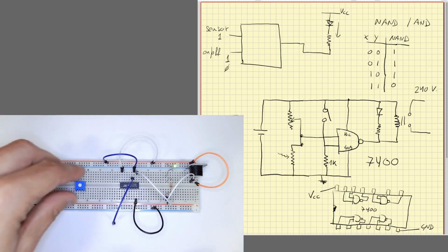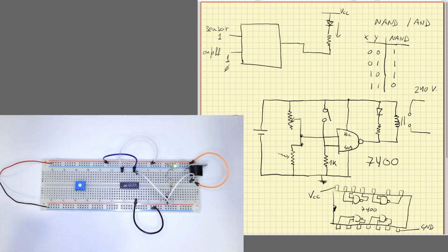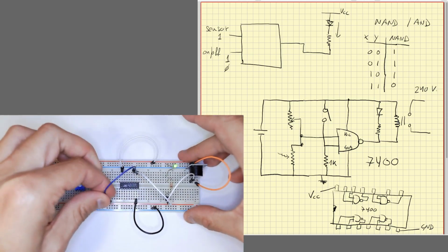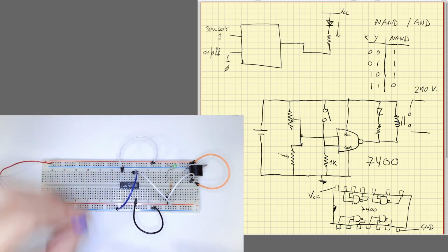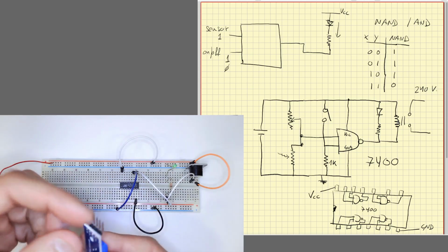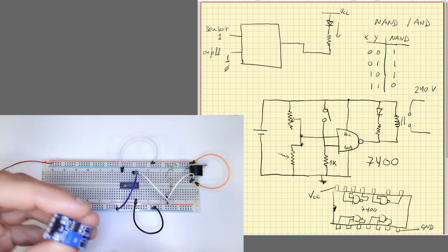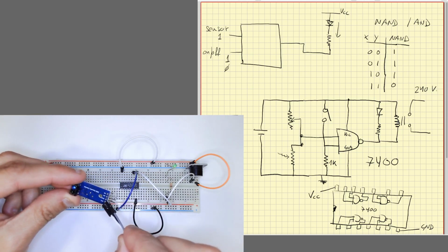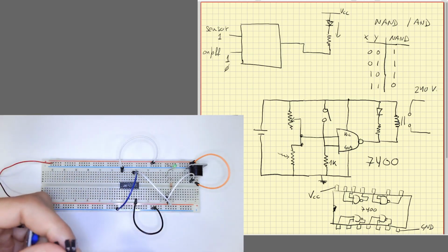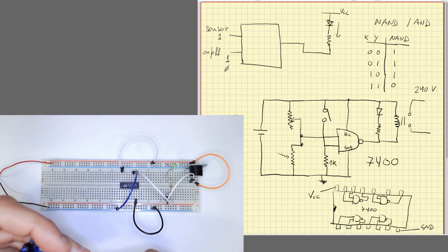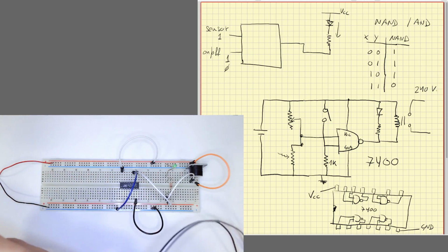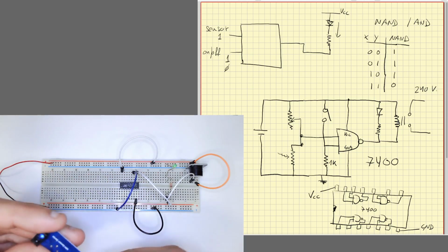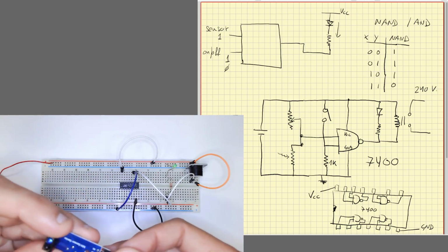We'll remove all this. We will switch our system off. And these sensors already have the terminal. We have to give energy to the sensor, so we have to use these VCC and ground terminals. So I'll use this cable. I will use this for ground, the white for VCC, and it has both a digital and an analog output.